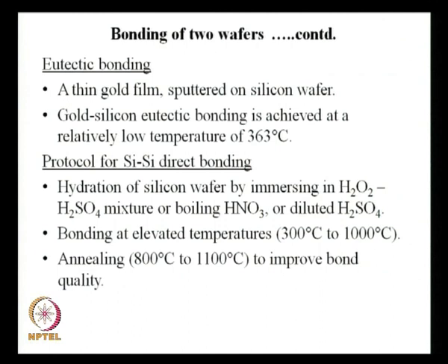Now, silicon direct bonding: there you have to follow a certain protocol. Protocol is something which I tried to summarize here. Hydration of silicon wafer by immersing in hydrogen peroxide H2SO4 mixture, or boiling HNO3 or diluted H2SO4. So, you have to treat this silicon material first by dipping it into a certain liquid,